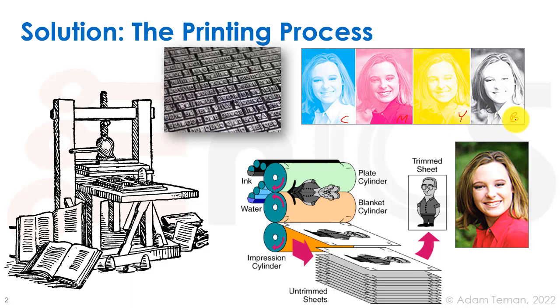That's a CMYK process, and then we break down the photo into these four parts of the color, and we run the paper through those four molds, and in the end we get our full colorful picture. The same thing is done with a VLSI process. We make our photo masks that each have a single layer or a single step or a single part of our design. It doesn't matter if we have one transistor printed there or a trillion transistors printed there.